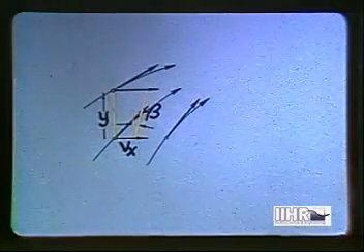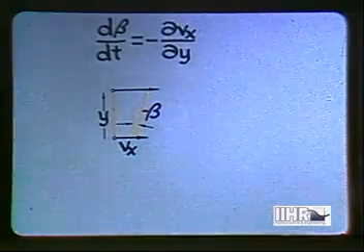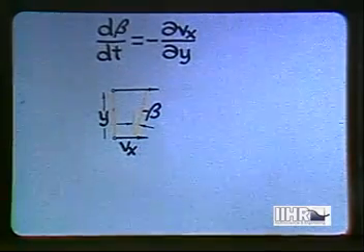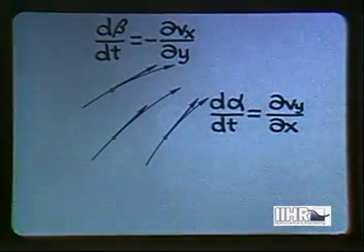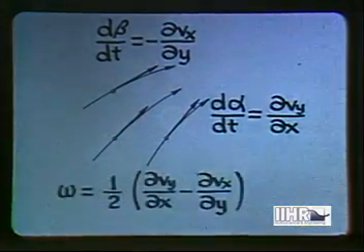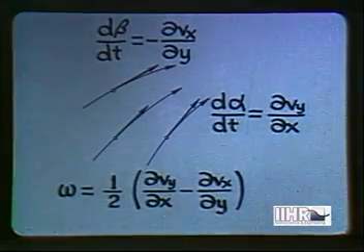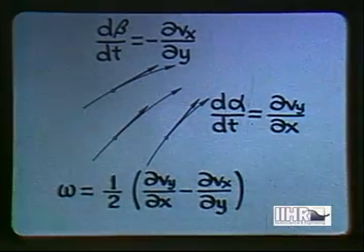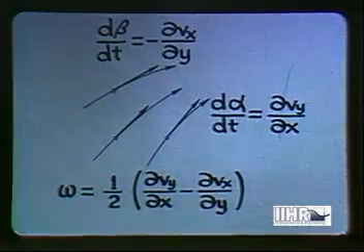The same is true of a line or stick in a direction that is perpendicular to the first, a negative velocity gradient now indicating rotation in the same positive sense. The net vorticity in a given plane depends upon the average of the velocity gradients in the two normal directions. This in turn would be indicated by the average tendency of two lines or sticks at right angles to each other to rotate.